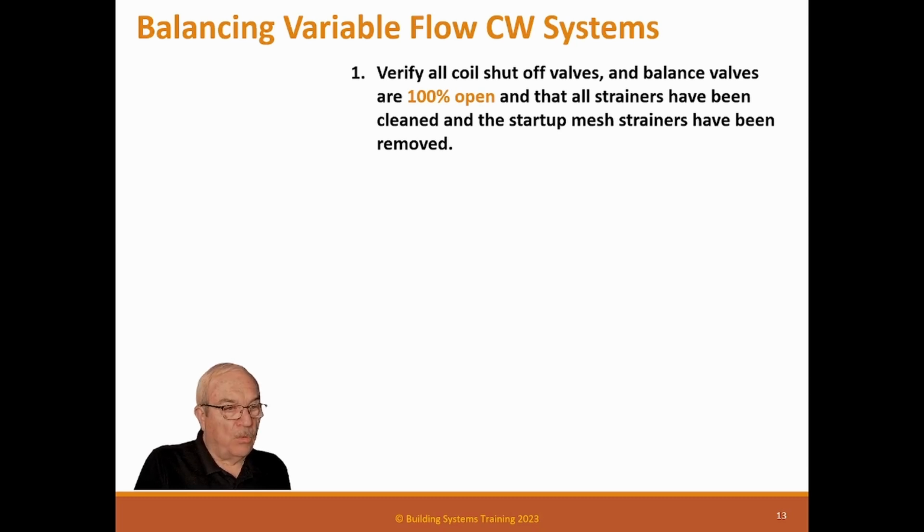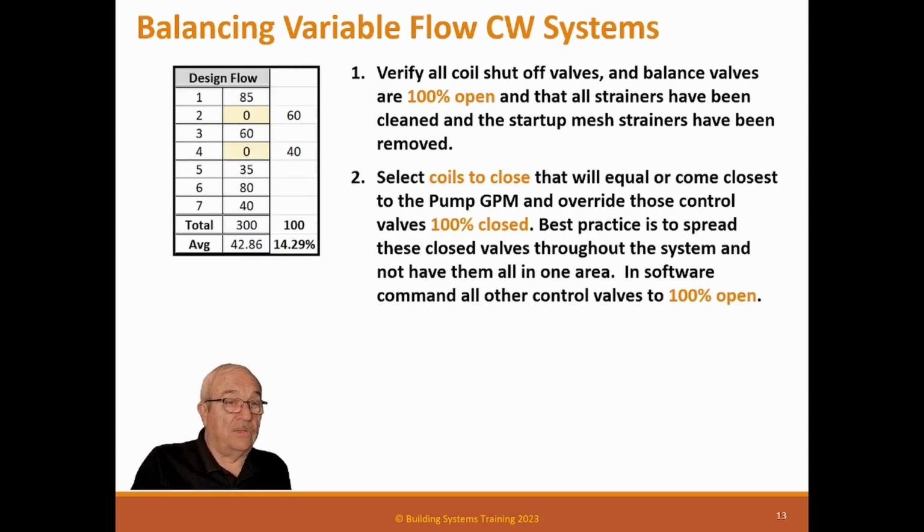And remember, in water systems, many times the larger strainers will have a sieve that's sized for the pump volute openings, and then they'll have a small screen inside that, which is actually a startup sieve. That's designed to catch all the rust fines and everything out of the system when they're starting it up and cleaning it. So by the time you get there, those should have been removed because they will put a lot of excess pressure in the system that you don't want.